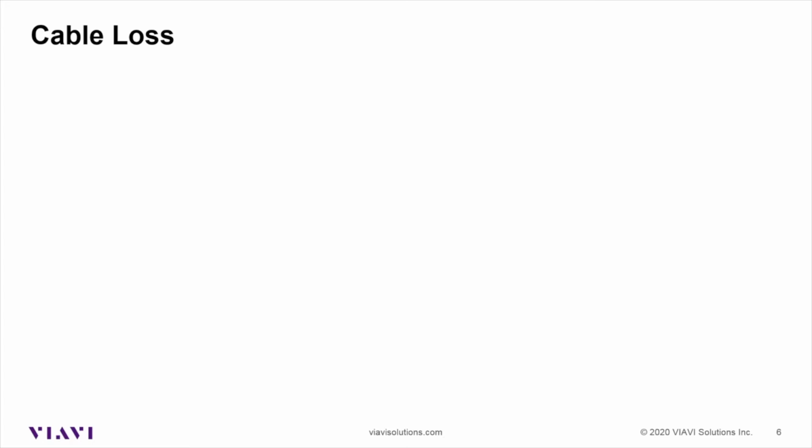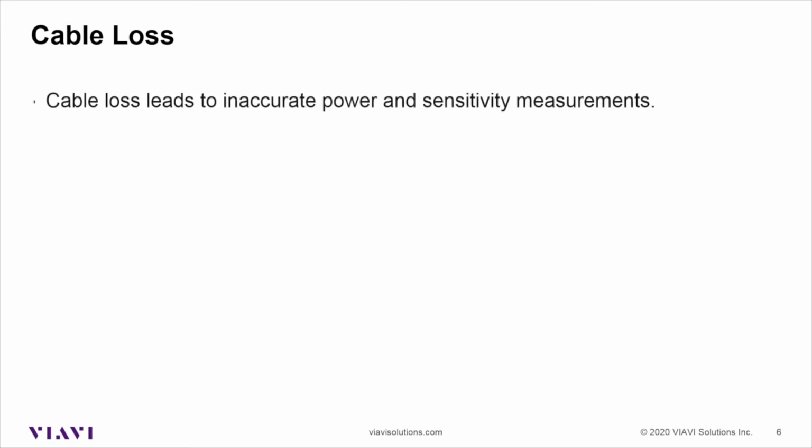So cable loss is one of the things that we'll start talking about now, I guess, with some of the do's and don'ts here. Cable loss is one of those things that I do spend a lot of time on. If you've ever talked to me on the phone, you've probably heard me talk about cable loss. And the reason I talk about it, and the reason it's so important to me, is that cable loss is the single most significant cause of auto test failures, false failures, or inaccurate alignments, or just generally, I guess, issues that people have with auto test or testing the radios in general.